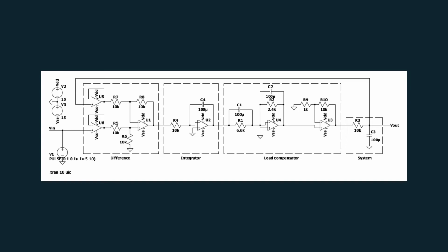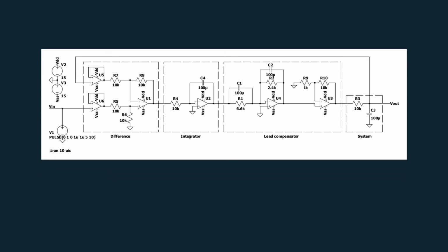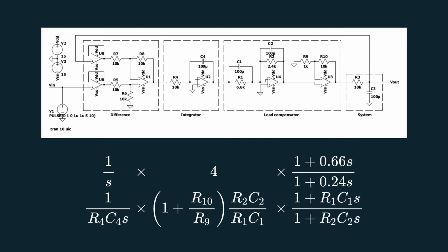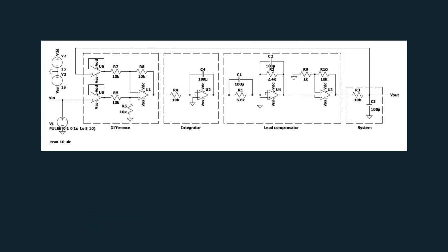I started by setting all the capacitors to a value of 100 microfarads. Then, by equating the transfer function of both the circuit and the designed controller, I managed to find the value of each resistor. The final step is the implementation on real hardware.